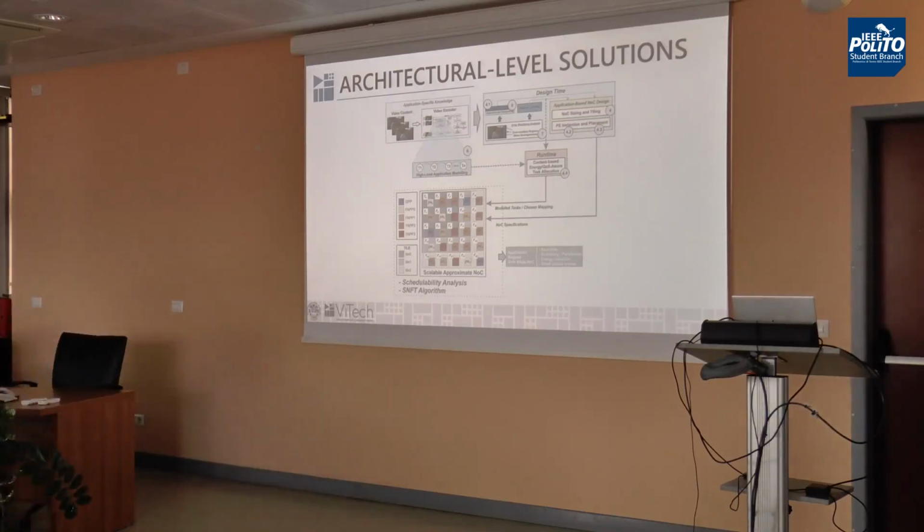And at the same time, we also need to do some sort of quality adaptive solution. And we started with this one, right? Here, what we have is a 5x5 network on chip with 5x5 processing nodes. Some are for memory access, so the upper one, the GPP, is not really processing, it's just bringing data and distributing. The other ones are solving our main algorithm problem, that's fractional motion estimation.